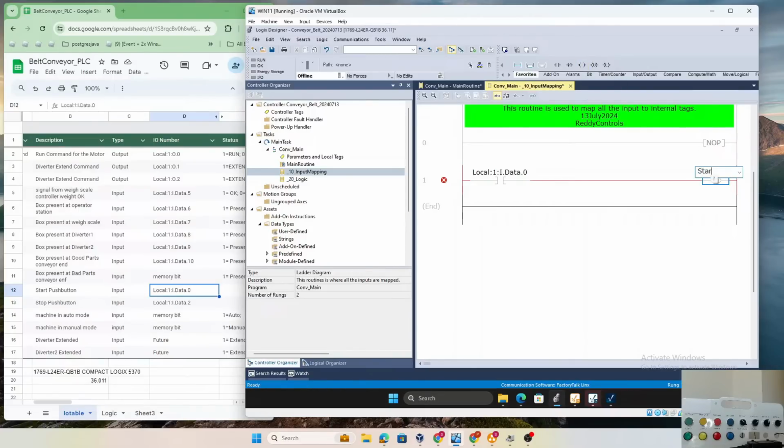So we go ahead and type start. And one thing we're going to show you is I cannot start a tag with 1, because all the tags need to follow the IEC 61131 standard, and part of that standard is that tags cannot start with a number. So we'll go ahead and try it.